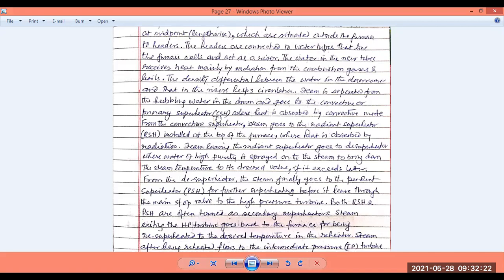So we have to control the heat with a water spraying system, or desuperheater. It is called the desuperheater. The desuperheater reduces the temperature of the steam itself to a required level by spraying 100% pure water, at room temperature, inside the steam itself, which will reduce the temperature to a considerable extent.